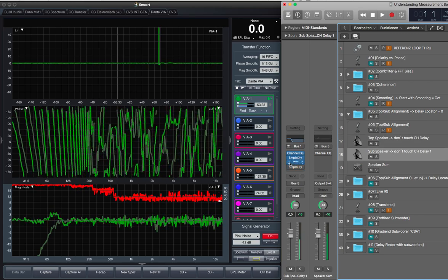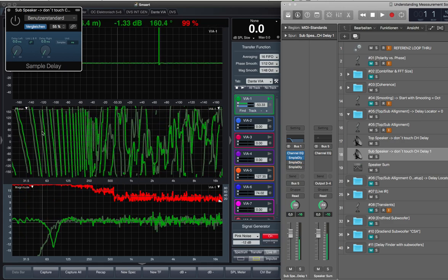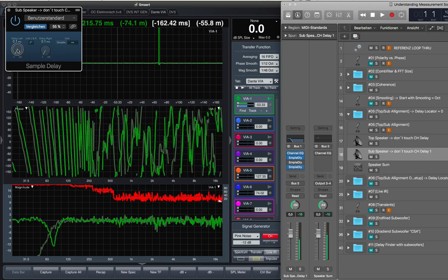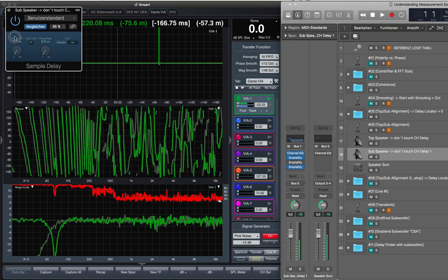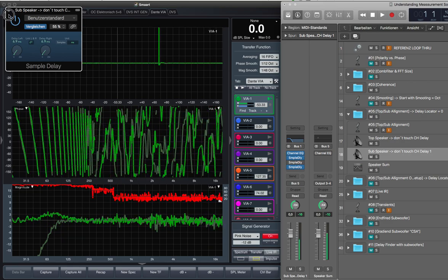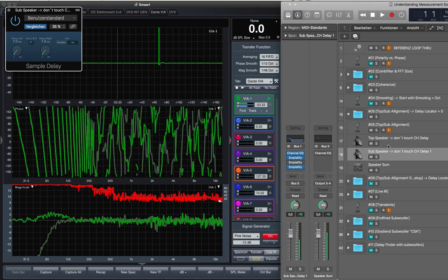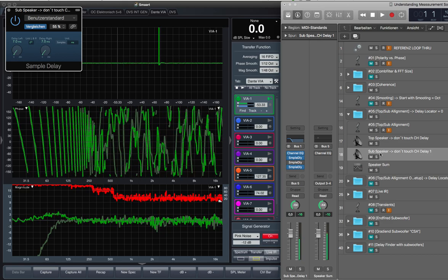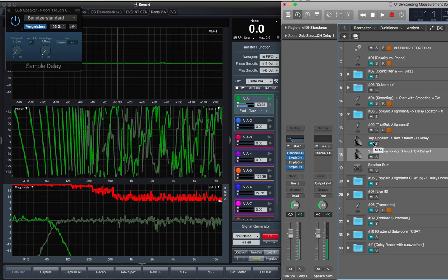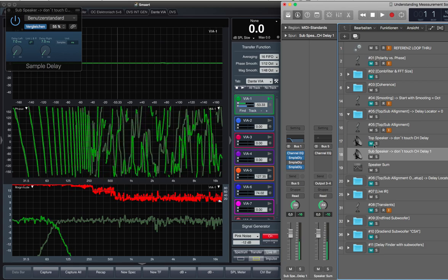In this example, I'm two times around the phase wheel, and in real life, we have to change this. How does it work? We add the delay, and then I increase the delay until these phase slopes perfectly match at all positions in the area, and this might be the case here. And switch on all speakers. In real life situations you have to mute the top speaker. It's just here in the electronic way this worked, so this is my bug, sorry.